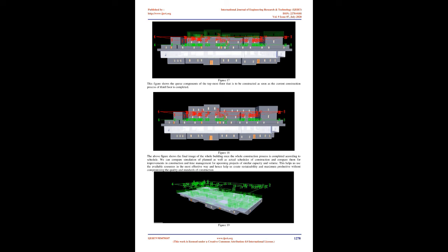The 3D model is then given its 4th dimension as time constraints. The 4th dimension, namely time constraint, consists of tasks and their corresponding start and finish dates. A total of 27 activities were selected to show the construction process floor by floor. On simulation of the 4th dimension through Navisworks Manage software, we can virtually assess the entire construction project from start to finish. This helps us make improvements in time management for the project.